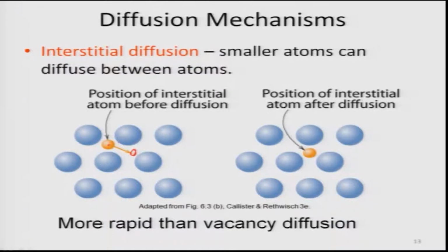But whatever the reason, diffusion by interstitial atoms is much faster, in fact an order of magnitude faster than substitutional atom diffusion, because of the availability of a large number of vacant positions and the size of the smaller atom.